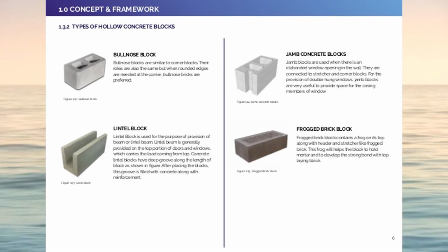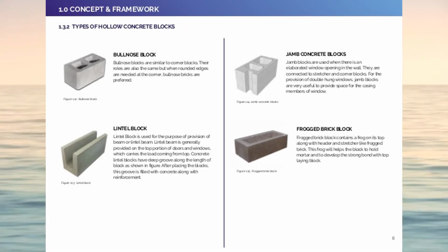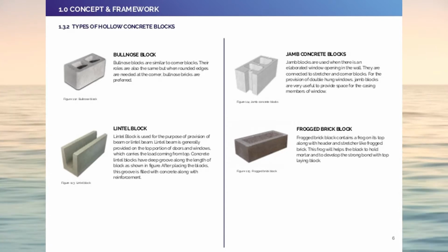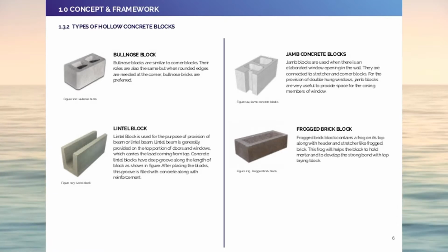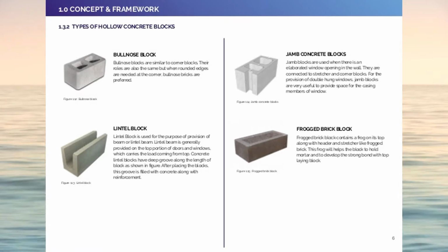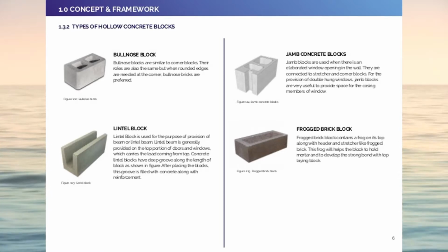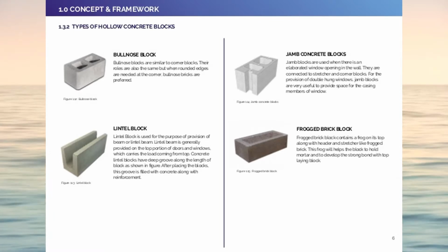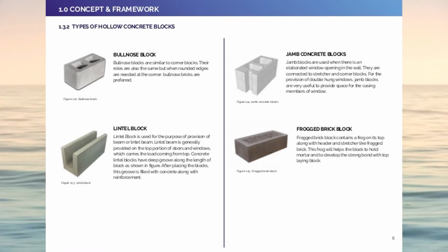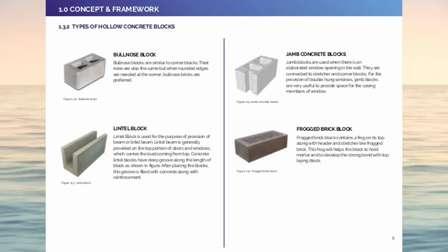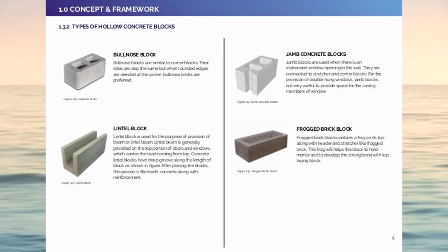Hollow concrete blocks contain void area greater than 25% of gross area. Solid area of hollow blocks should be more than 50%. The hollow part may be divided into several components. They are manufactured from lightweight aggregates. They are lightweight blocks and easy to install.